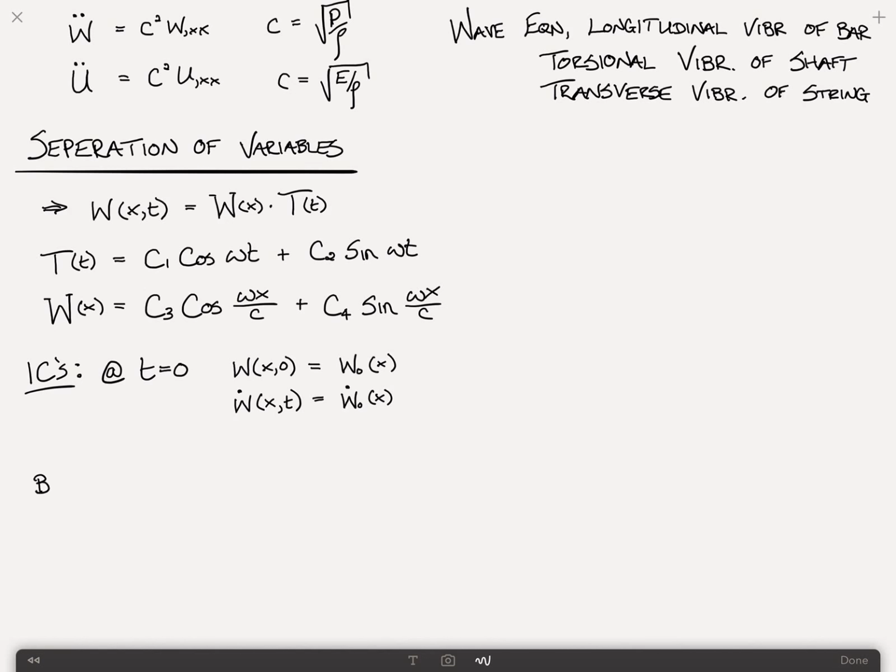And the two boundary conditions that we typically find, you can have some other exotic ones, but the most common is that the string is pinned at both ends. I remind you that we can't have a free end in the case of the vibrating string, because if one of the ends was free and there was no traction applied, we would lose all the stiffness. Why? Because this P would go to 0. In other words, we need tension in the string, so the string must be fixed somehow at both ends.